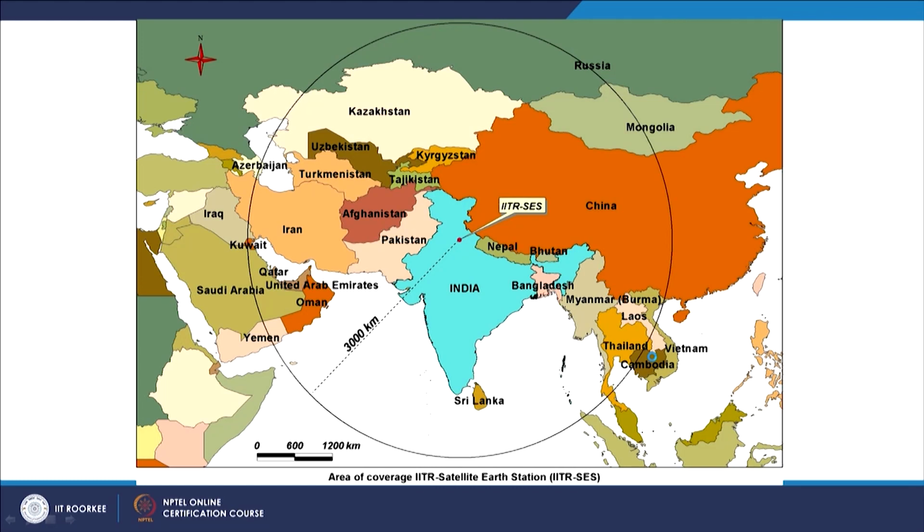It is a scanning device on the NOAA satellite. So, this AVHRR sensor scans line by line, and the data is transmitted directly towards the earth, and through these earth stations we can record the data. Since the spatial resolution is coarser in case of NOAA AVHRR, the swath is quite wide. I will be showing an image also.